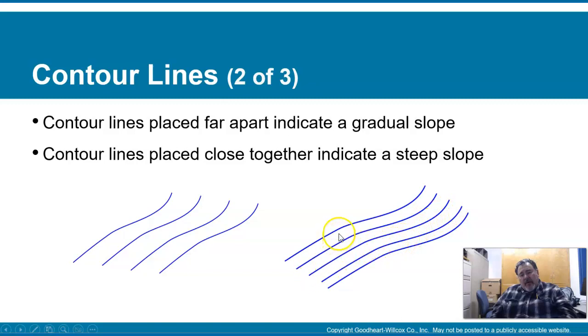And so you see how they almost look like a hill. It's forming a hill going downward in the slope. So it's showing you this shape, and the lines show you how the land is dropping in elevation. You can see how these lines are closer together and these are more spread apart. Well, that's saying that the land is dropping faster as opposed to dropping slower.